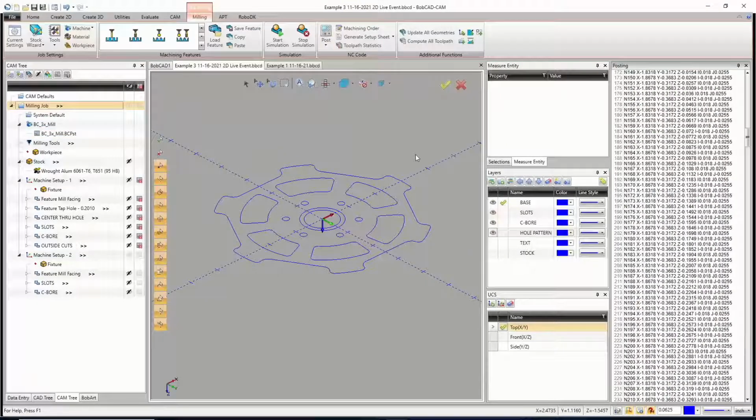If that doesn't work, I've had it happen before where you just won't post. Save your work, close BobCAD, open it back up, and try and post. Sometimes it's as simple as just restarting the program. Usually it happens to me if I let my computer go to sleep, like when I go to lunch and my computer falls asleep. But try those out. If it's still not posting, if it's specifically this part that's not posting, then I'm not sure. All your options might be set to post yes, no.